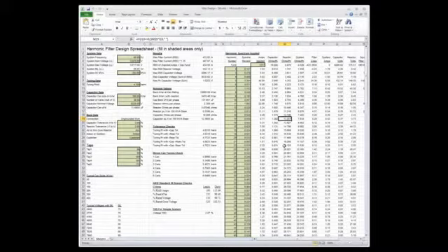I know there is a trend in some filter applications to use internal fuses. I know that they're there in certain cases. In my recommendation, I want to see that it's open. I want to see an open condition. And so that's why I've always preferred the external fusing.